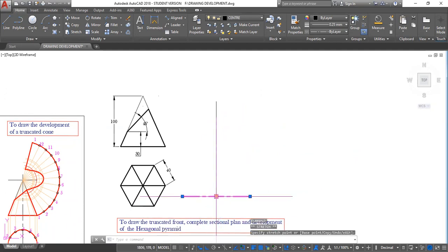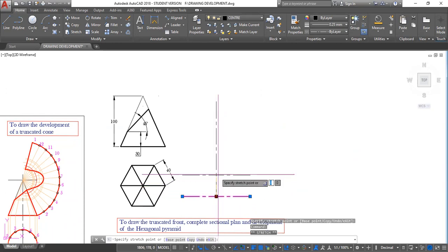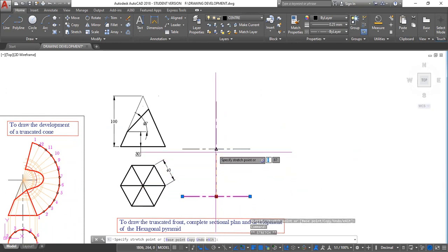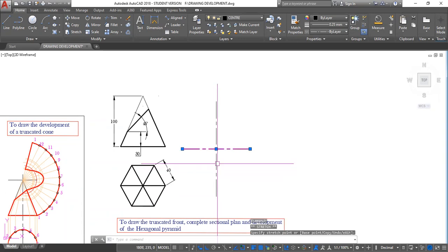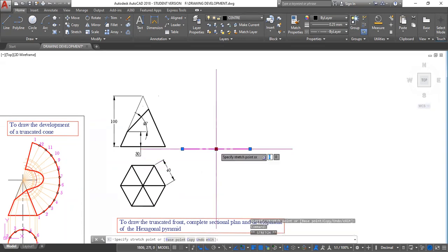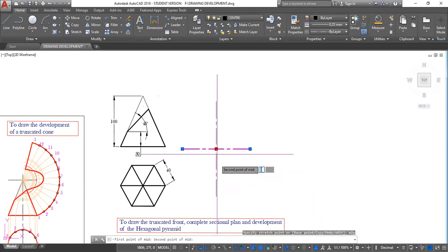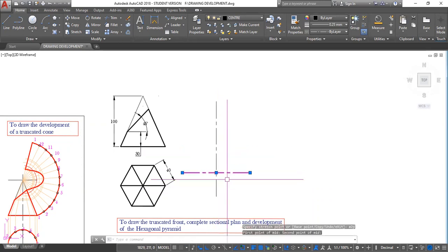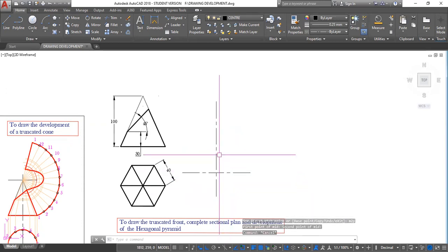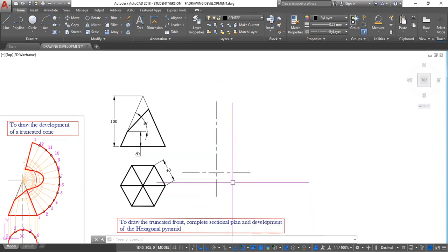Next, I want to move this some distance away. So I go there and I bring it up. I'll be tracing this point. Sorry. No, it wants to stick at a specific point. So I'm going to use a special command called M2P. M2P, enter. Then I specify click here and there. What that does, that allows the line to snap at the middle of 2 points.